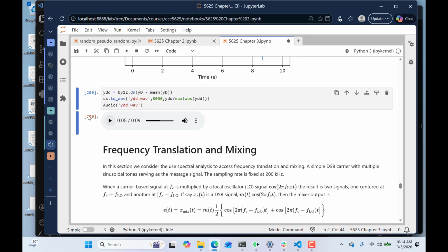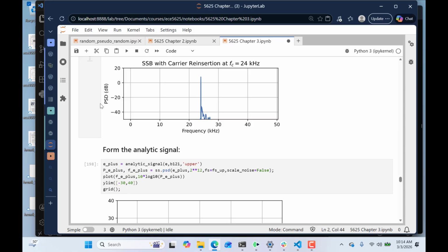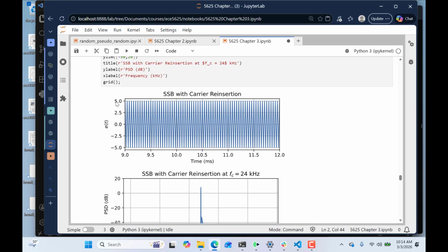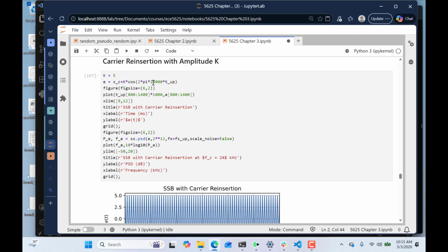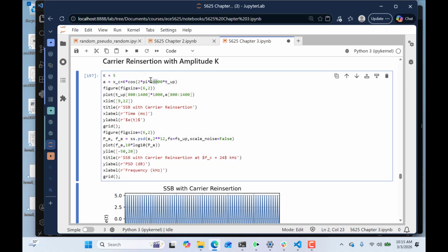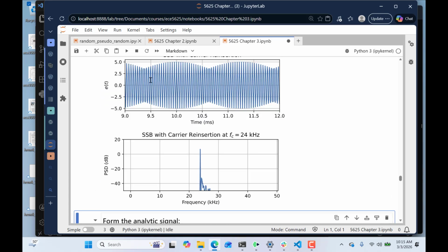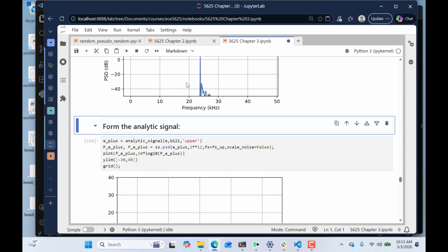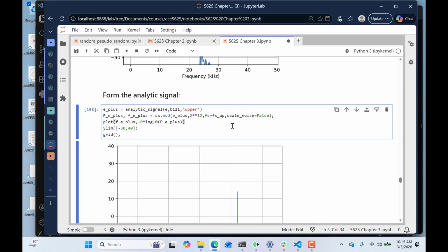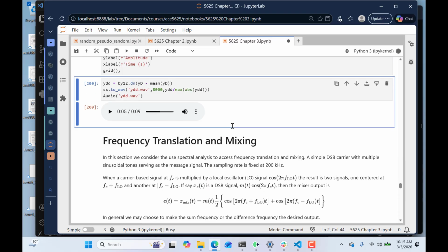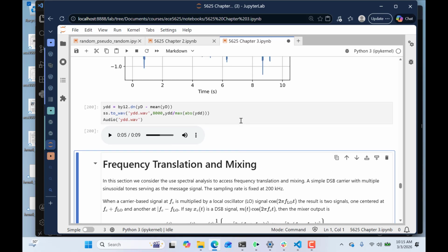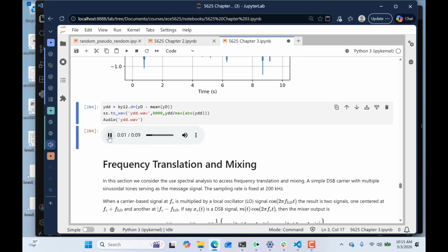I mean, again, if we're not perfectly coherent, though, which is what we would not be at the receiver, our demod here might have the same phenomena that we had before. We might be off by say 200 hertz in this case. And what we'd be hearing then as we walk down this path. The little tales they tell are false. But it still works, and this is the more likely way the amateur radio does it with the carrier reinsertion technique.